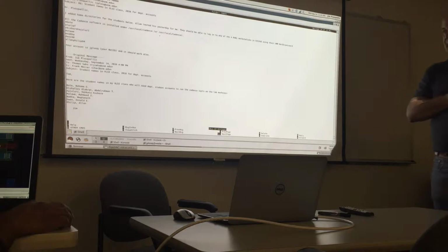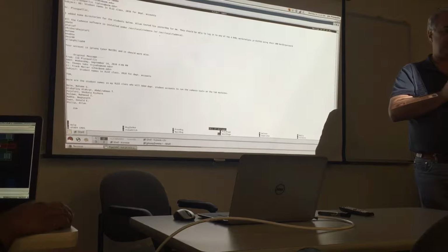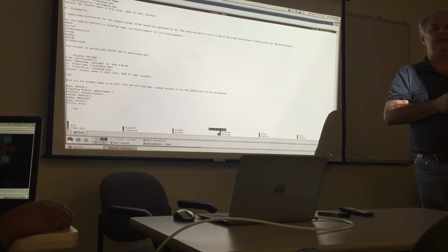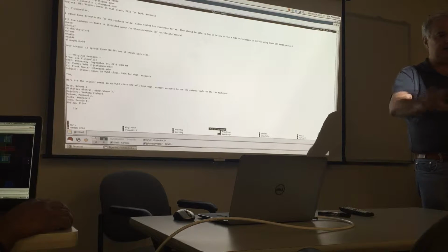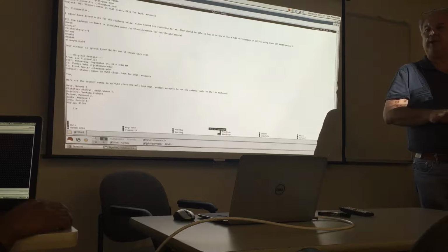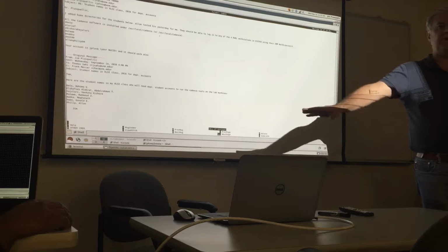I use what's called inherited power and ground connections. I do that because, when I was on sabbatical, that's what they did. They said we need this because we have multiple power domains. When I came back, I just continued to use it. It comes in useful when building chips because you may choose to connect everything to the same power rail, and by default it will let you do that.